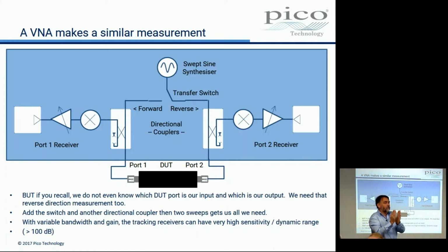And when we look in narrow bandwidths for what's there, we're going to eliminate noise. So a tuned receiver can be working down to more than 100 dB down. Now 20 dB down is 10 times down, isn't it? And 40 is 100 times down, and 60 is 1,000 times down. So 120 is 1,000,000 times down, right? So you can have a very, very sensitive receiver here if it's a tuned receiver.